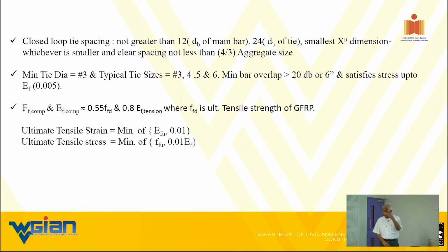Right, top to bottom. You see, this is particularly important in your case because you have end effects where you are applying the load, so you have much higher load concentrations than in the middle 70%. The top 10 to 15% and bottom 10 to 15% are far more severe than the mid 70%. So you can get a good profile of that.